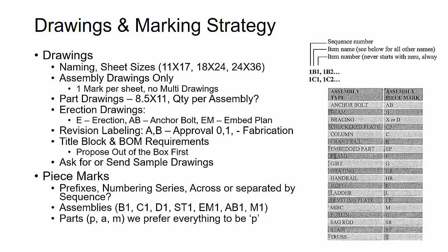All right, piece marking is also really a big deal. Make sure you understand whether piece marking is going to be separated by sequences or phases, what the prefixes are, and what the labels are. I have seen time and time again that detailers using the 3D modeling and detailing software just start putting things in the model and forget to change this or get it figured out, and then they have to come back afterwards, even after they're connected, and start changing and modifying this.